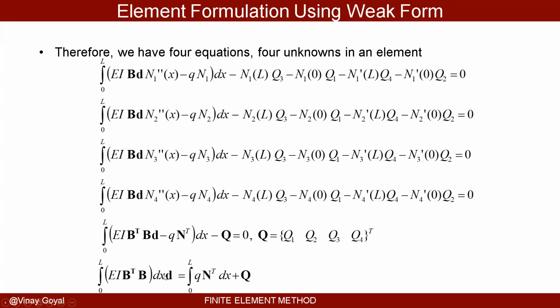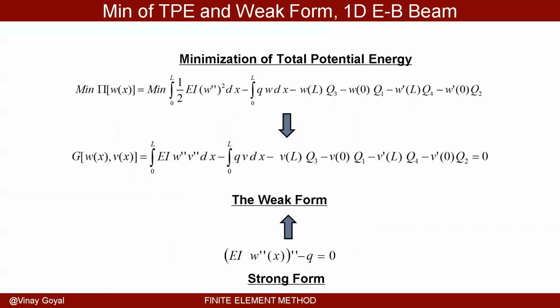And so now you have D bold, which contains the unknown coefficients. They're the nodal quantities that are unknown. All this stuff here is numbers. The force you apply is a number. The concentrated force you apply is a number. So the only thing that's unknown is D bold. And that's exciting. We're able to turn a governing equation into an algebraic system of equations.